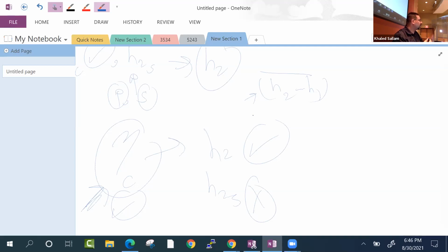We go into our design and basically say, this is a horrible calculation. They assumed isentropic compression, for example. Is that true? That's not true. But then you're trying to find out how far it is from real life. Maybe the isentropic efficiency of the compressor is like 95%, and so the loss is not really that big a deal. So at 5%, what's 5% between friends? Nothing. So at 5%, the assumption was okay. Or is it like 20%? And that's a big deal, right?